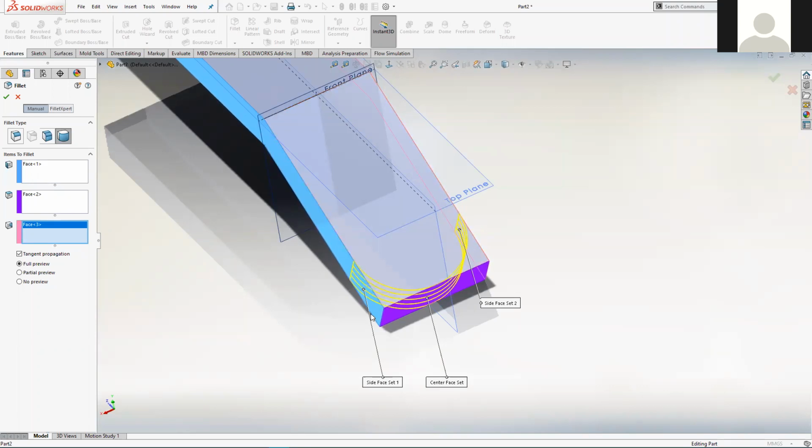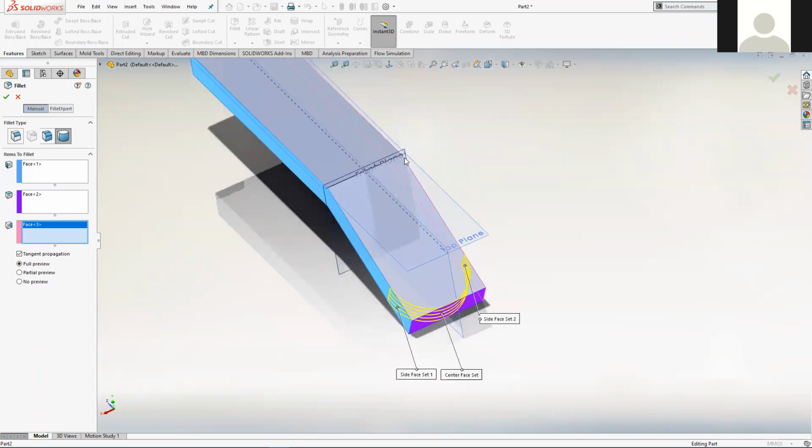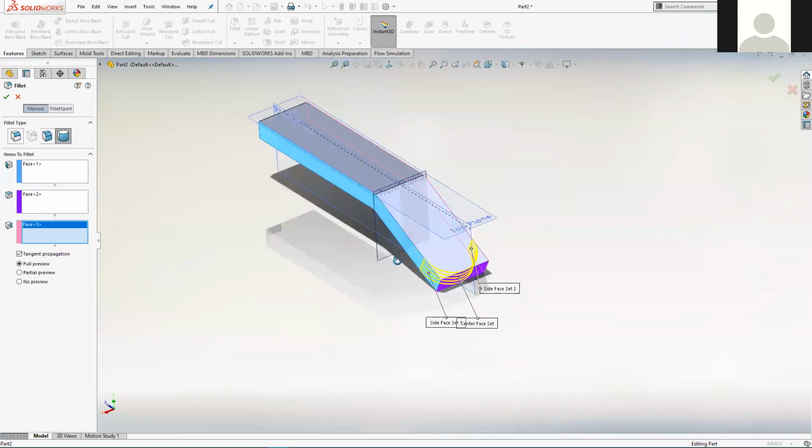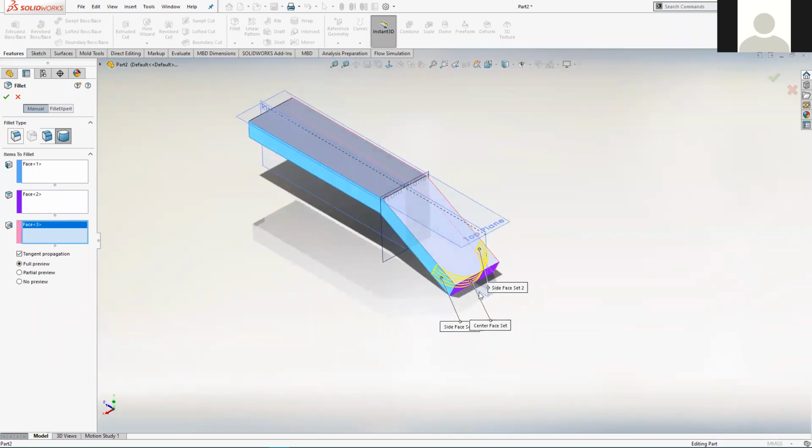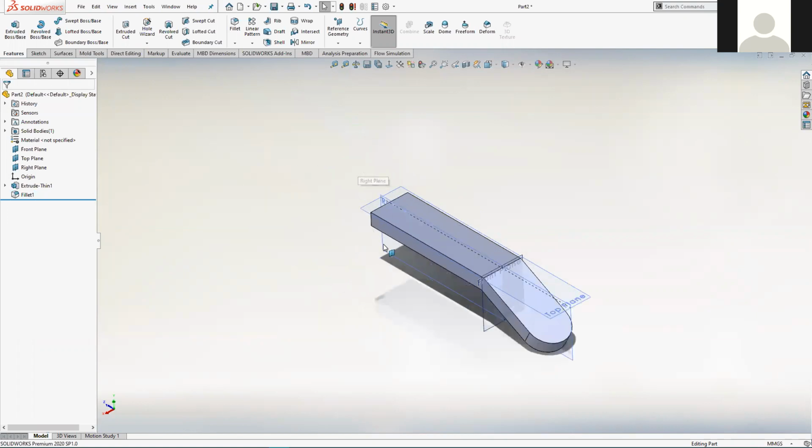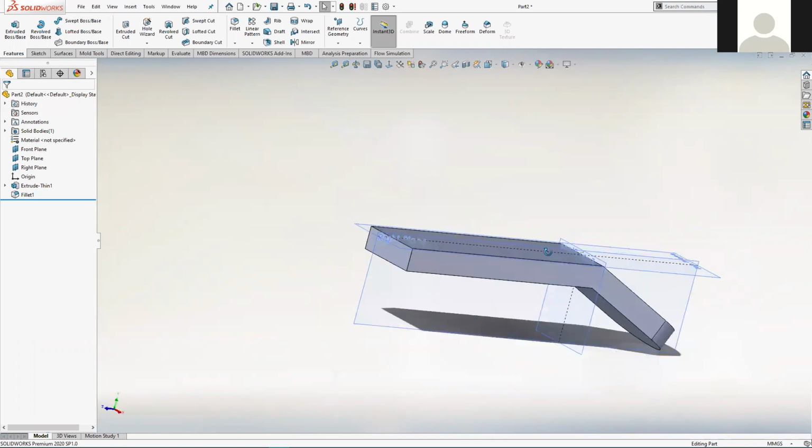So yeah, it's quite useful in instances such as this, where you don't want to manually set a radius of curvature. You just want it to adapt to whatever width your part happens to be at. So it allows you to edit your part in a manner where this fillet will always adapt to that change in size. So we're happy with that. We'll click on OK, and then we'll put a second one of those full round fillets in as well.